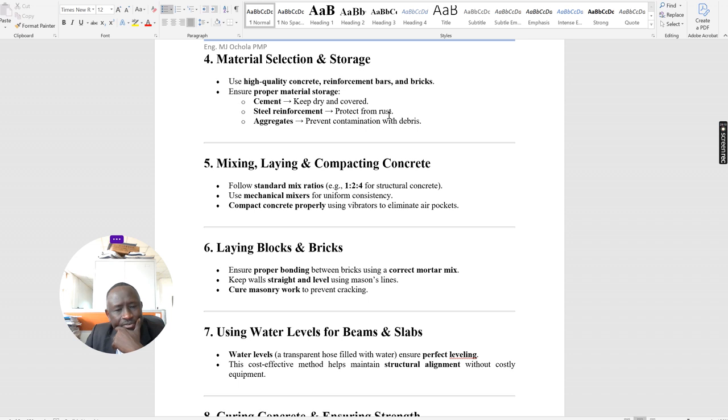These bays have compartments. They have concrete bases, and because some of these aggregates come in sizes like maybe 8 to 10, maybe 10 to 12, maybe 12 to 14, you try to put them in different bays. So during the batching or mixing, that's when you can get different portions from different bays or compartments, then you put them together for mixing concrete.